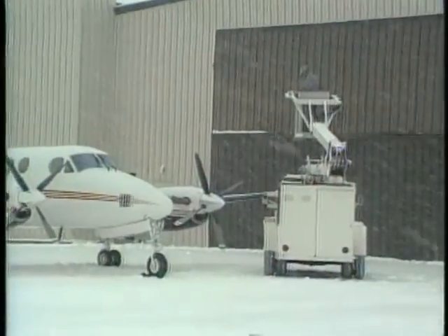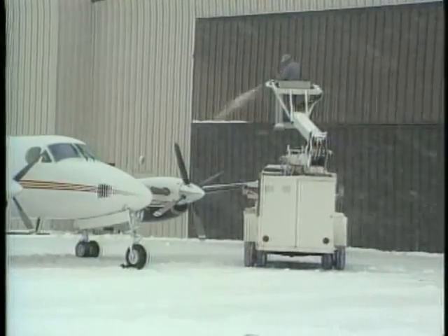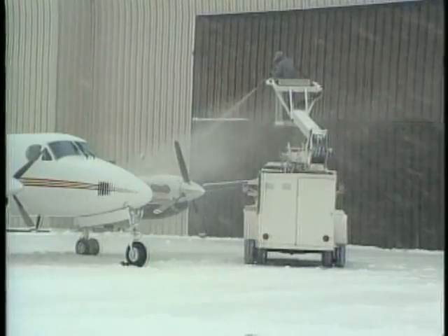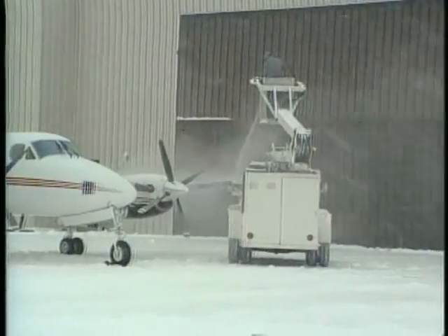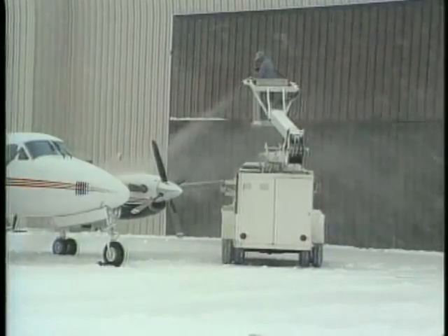Windshields may be protected with alcohol, but normally they are electrically heated. Tiny electric heating elements are laid in the windscreen or windshield panel to heat it up and melt any ice. Before flight, anti-icing chemicals may be applied to the airframe, propellers, and windshield to lessen the chance of ice adhering to these parts. Used together with anti-icing and de-icing systems, these chemicals can be very effective.